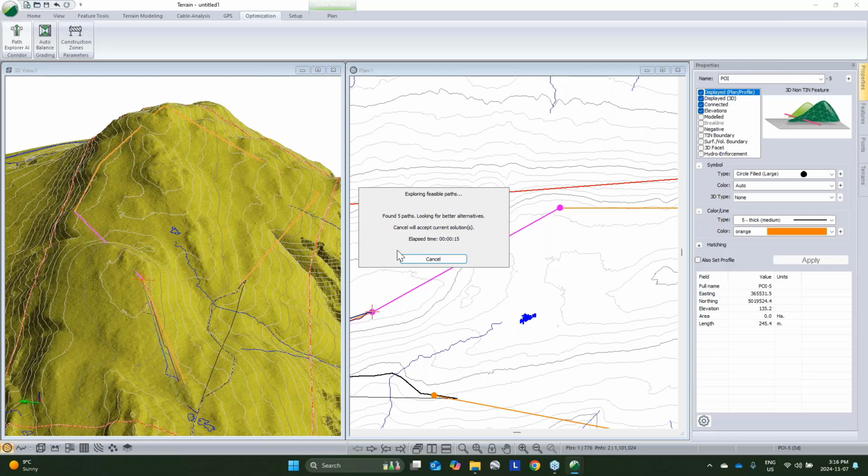Okay, we have one, Matt, already. The question says, can I import an AOI from GIS? Yep. So for that, just like I brought in my shape files for my points of interest, we can bring in a shape, we can bring in a KML, DWG, etc. So we can bring in your vector data from all the standard formats. Yeah, and I just drew it in because I didn't already have that existing in another format.